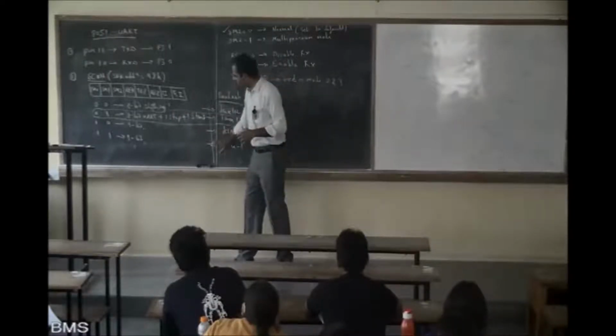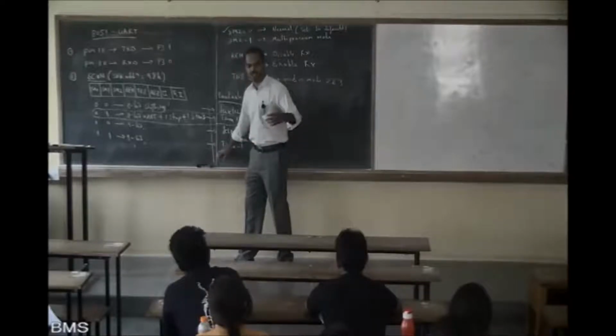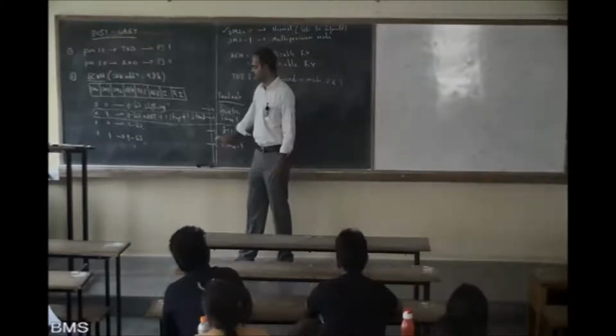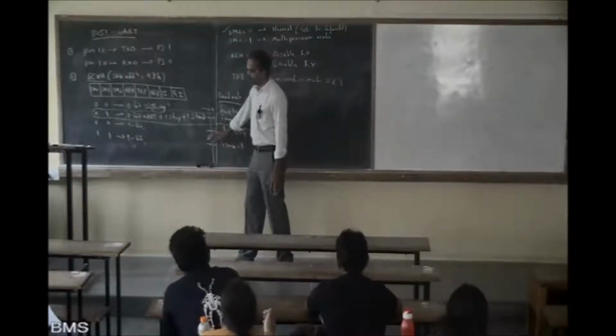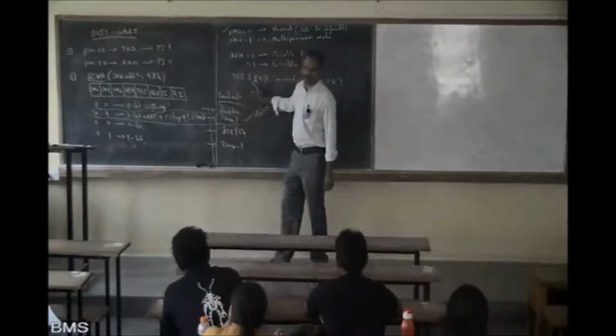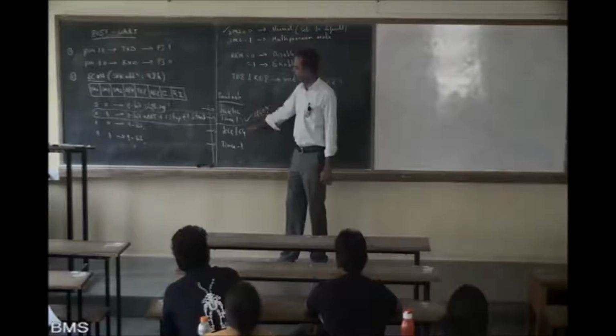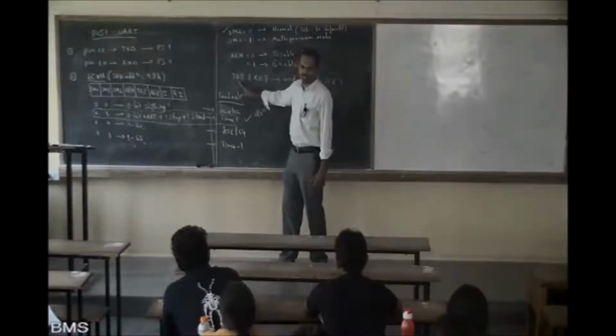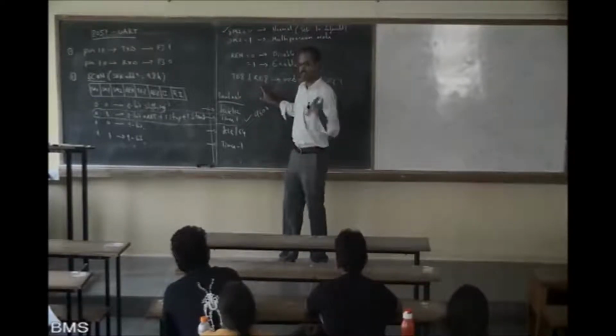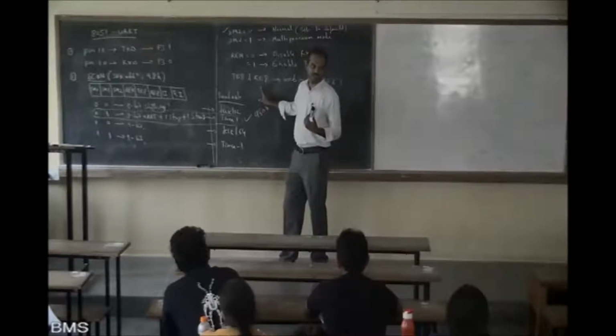As it is right now, we are not discussing mode 2 and mode 3, which, according to your syllabus, is not there. So we will not worry about this. This is just for your information. What is this TB8 and RB8? It's the 9th bit setting when you are transmitting. When you are receiving, the 9th bit will set this.